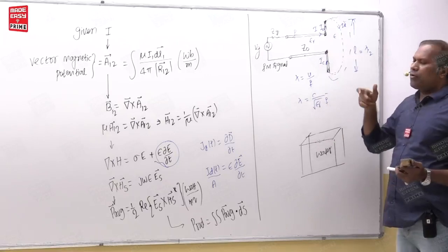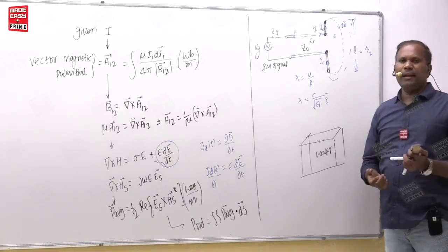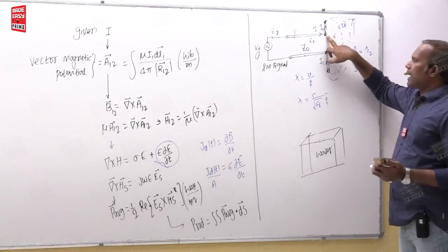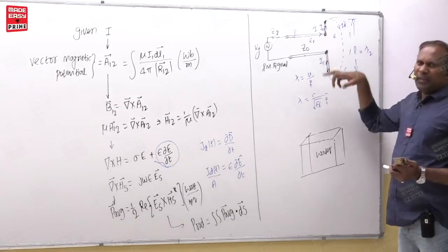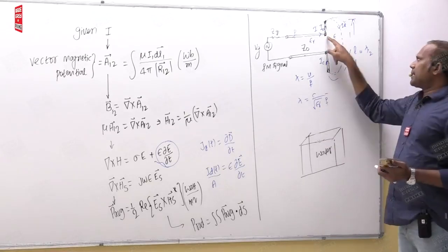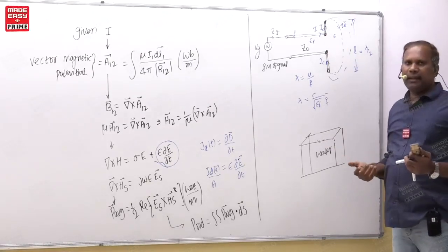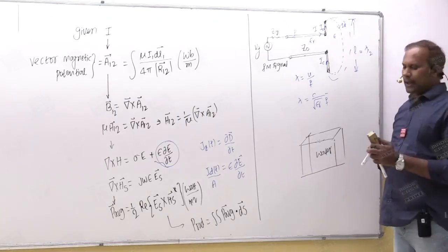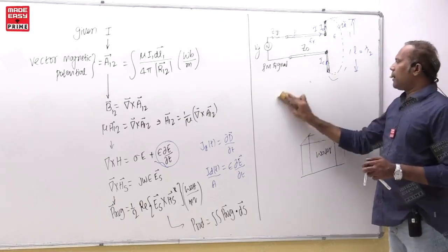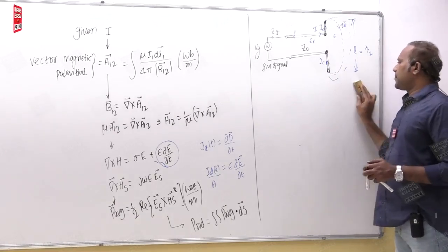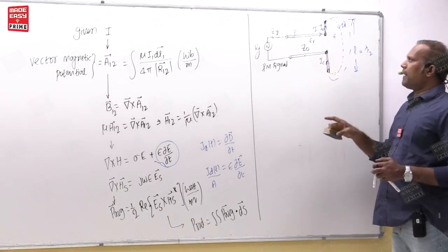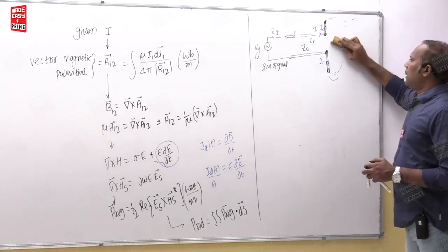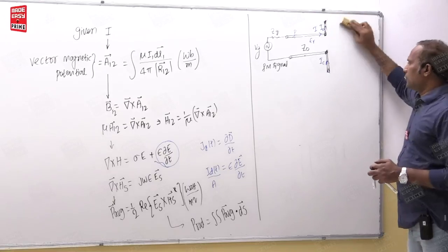Similarly, when a very high frequency signal is connected to these conductors, the disturbance is very high. Those conductors cannot handle that high frequency. They try to send that high frequency signal out of the conductor. They observed that whenever the frequency is, for example, f, then calculate lambda, and when the physical length of the antenna approaches lambda by 2, then they start radiating, students.